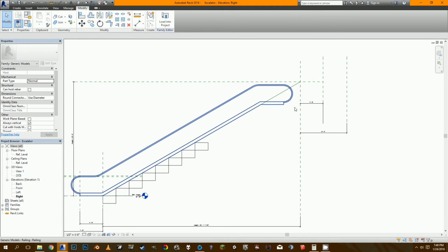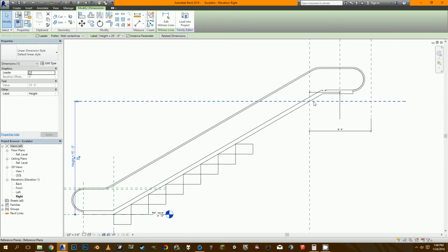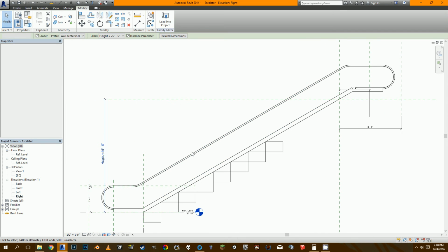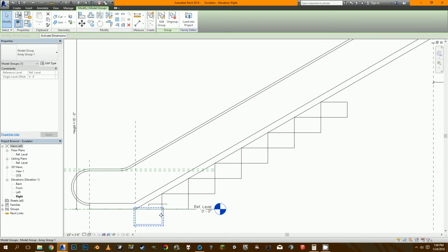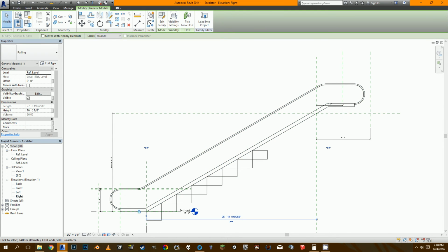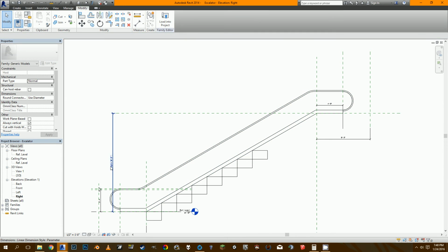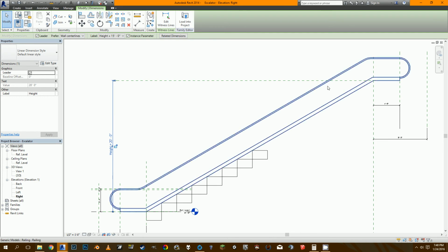And actually, again, if I adjust the height in this, you could see this intersection changes, but the railing doesn't. So just like we associated one parameter from the nested family into the main, we have to do that with the railing. So if you see here is height, we're able to just change this, and we don't want that. We want that to be whatever this is. So just select both of these and then click on the associate family parameter here and then pick height. And you'll see now they're both in tune. So let's make this 20 feet. And again, they both extend.